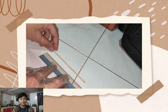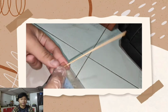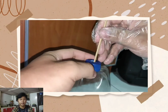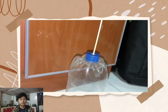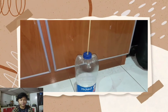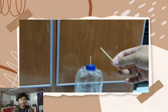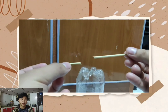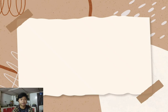Procedure. The first step, measure the dimension of each test specimen before and after test and fill in table 1. Mark the gauge length on the test specimen. Number 2, switch on the machine. Number 3, mount the test specimen in the grips of the machine. Number 4, apply and record load and the corresponding deformation. And the last one, number 5, repeat step 1 to step 4 for various types of the test specimen.